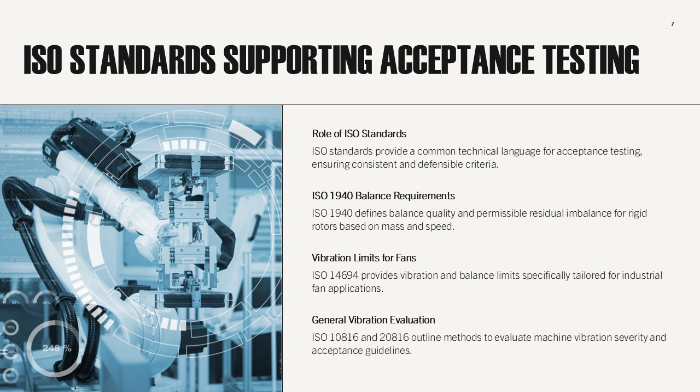rotors. This standard specifies permissible residual imbalance values based on rotor mass, operating speed, and balance quality grade. ISO 1940 is particularly important for acceptance testing of motors, fans, and other rotating components that have undergone balancing during manufacture or repair. Another key standard is ISO 14694, which provides vibration and balance limits specifically for fans used in